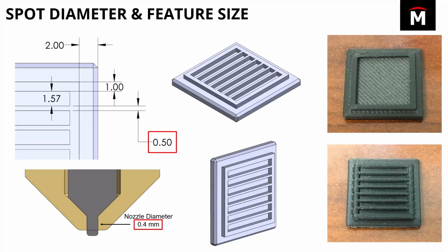Now by printing it vertically, each of those gray lines being 0.5 millimeters, printing at 0.1 millimeters means that each one of those gray lines has 5 layers. So it's going to print much more successfully. That's where you can see how Z-axis resolution is more accurate, a little more predefined, versus the XY. And we'll see in more detail why that's the case.